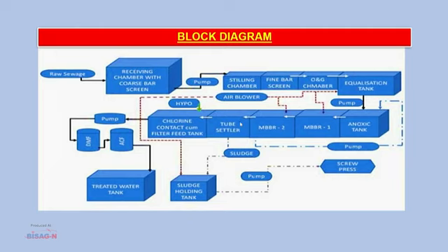Then comes stage 11, aeration. A stainless steel coarse bubble air grid will be used in the process tank to provide the oxygen. The coarse bubble design offers the highest oxygen transfer efficiency in the MBBR process, and it is a simple, reliable system with no moving and electrical parts in the tank. The header and lateral type air grid is placed at the bottom of the tank, and the holes will face the bottom of the tank so that air first strikes the floor and then rises upwards. It avoids creation of any black pockets in the reactor and settling of sludge.